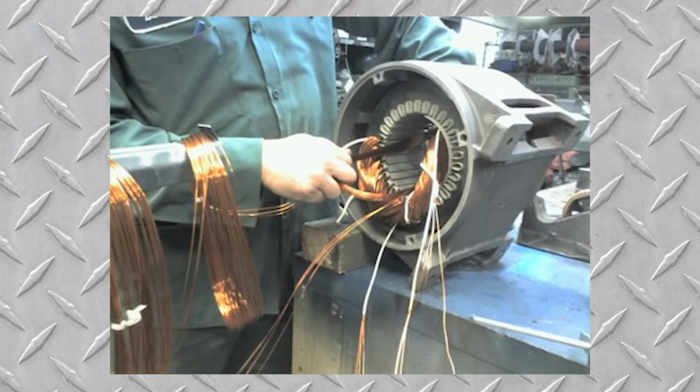Well, that may be necessary because your plant has to get up and running. So the real trick here is to never rewind a motor more than once. I recommend that once a motor has been rewound, you take a magic marker and put RW in big letters on the motor, which tells you that it's been rewound. And this tells you that you should have a replacement motor available, and that will reduce your downtime. Now, this is going to pay off. And although not many people do it, it's always a very good recommendation to make.